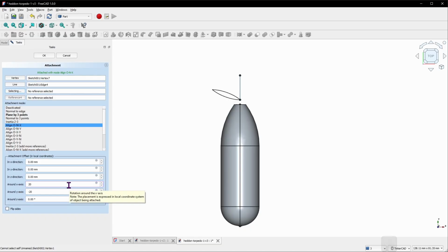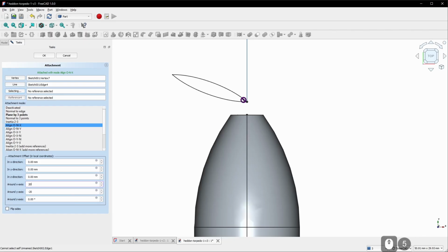And the very last thing I'm going to do is we're going to extrude this blade and merge it with the other parts of the prop assembly. And I want to maintain some of the skinniness at the beginning of this prop. And so in order to do that, I'm actually going to push this thing out in the X direction a little bit. So let's say 1 millimeter.